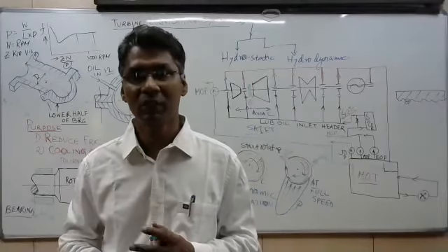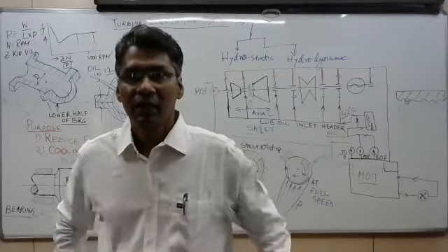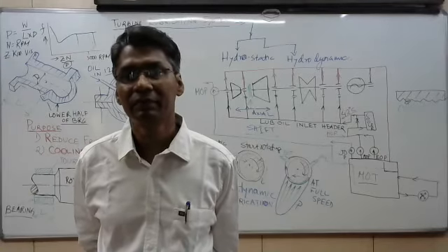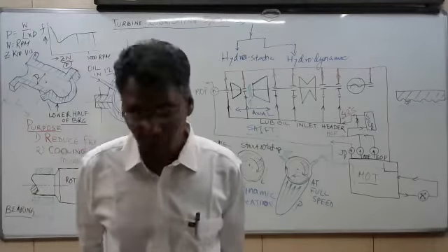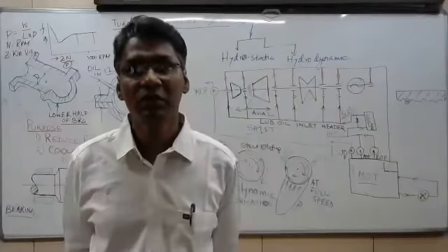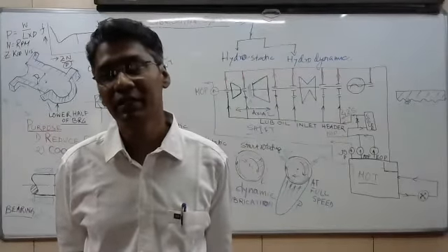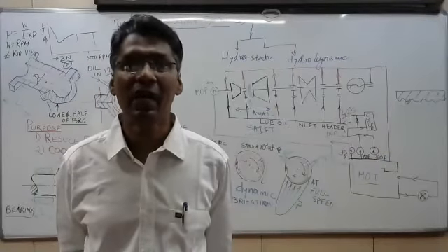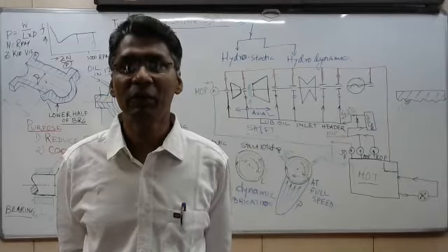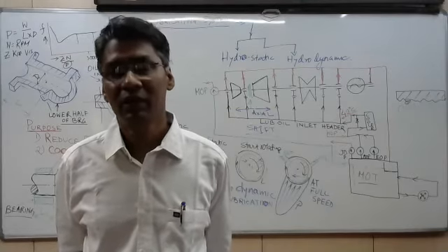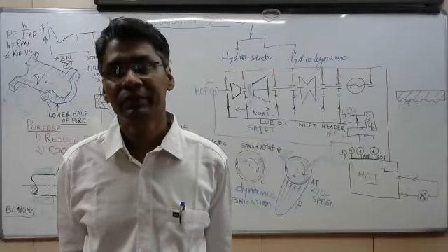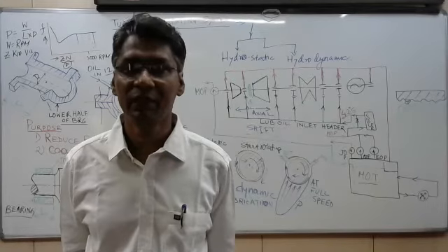Question from Ajit Kumar Singh. If the AOP is not developing the required pressure, what may be the reason? If there is a suction strainer inside the pump, it may be choked, so your AOP is not developing pressure. If it is not developing, another standby AOP will start. Then you check whether your pump suction is properly cleaned or not. Once one pump is overhauled, it will give you the required pressure. Next.